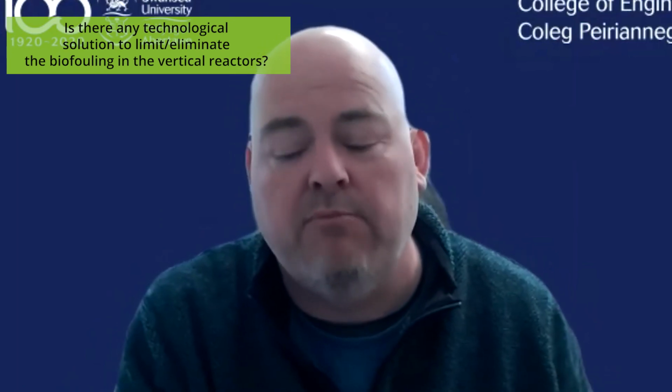Similarly, gas exchange. In this particular reactor, we did all of our gas exchange in terms of introducing CO2 where the pump was. That means as you go along the length of the serpentine reactor, you get a pH change, because the algae consumes that CO2 as it runs along the photo section of the reactor. So what we could do there is have multiple injection points for CO2 so that we maintain the pH more consistent throughout the whole internal volume of the reactor.